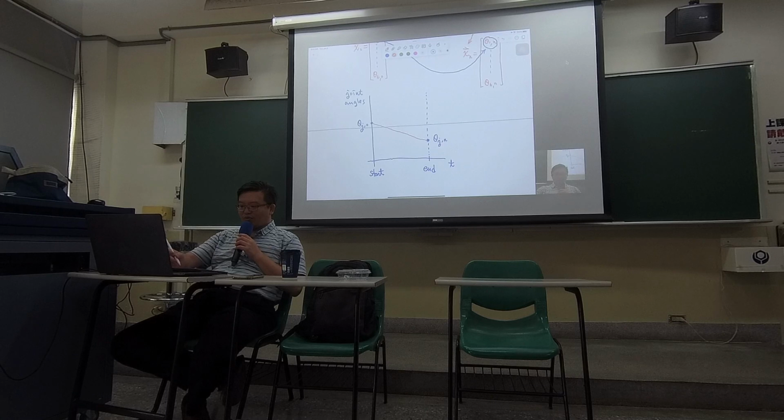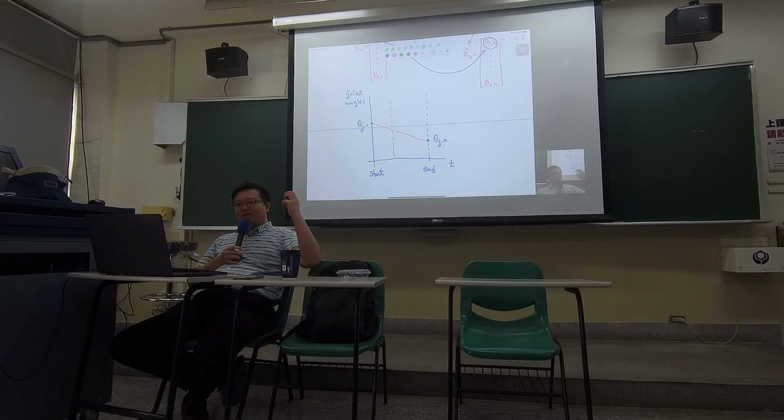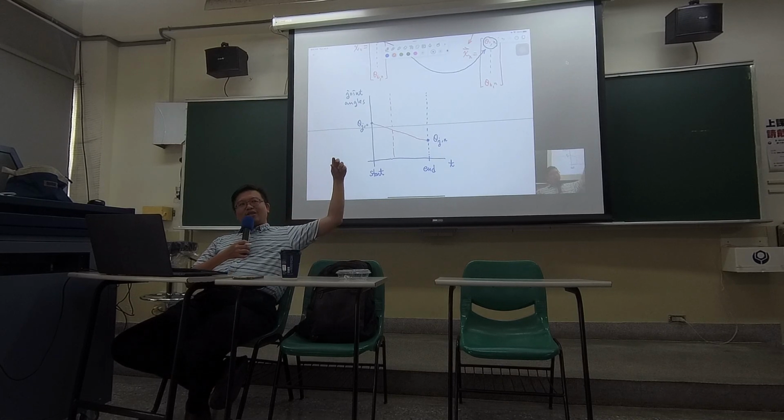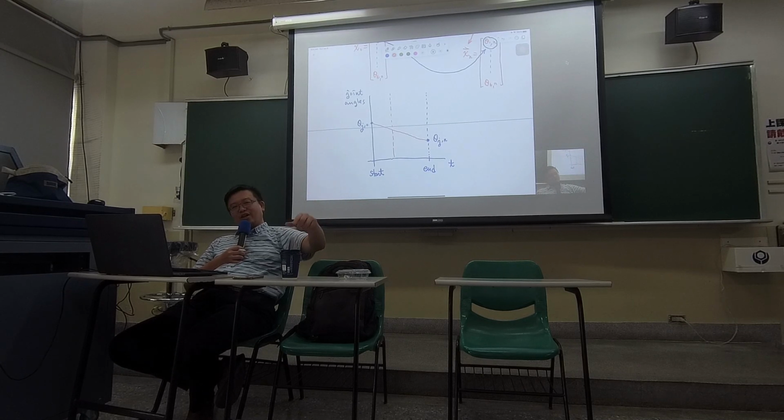However, somewhere at the middle, it's gonna be some combination of all 6 angles, but you have no idea how it looks like. So that's why if you say this is a starting configuration and this is the end, you know the joint angle combination at the start, you know the ones at the end. You ask every motor to rotate linearly from its starting angle to the final angle.